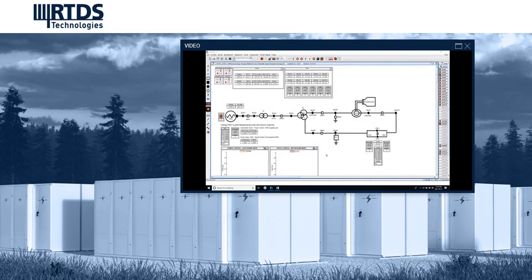The real-time simulation operation of the 300 megawatt variable speed pump storage simulation model will be demonstrated. The configuration uses the doubly fed induction generator connected to the grid. The back-to-back converters have a grid side control for regulating the DC bus voltage and a rotor side control for regulating the DFIG power and speed in generation and pumping mode.